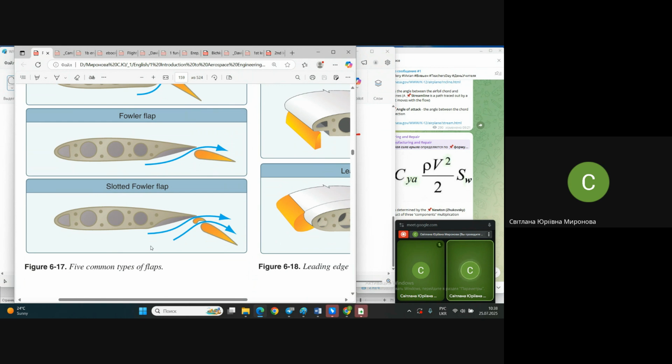That is a mechanically extremely complex thing, and here you see two links of the flap, like two pieces, but really it may be three and even four. The typical decision is three for big airplanes, and next we might see it in photos of airplanes. This slotted Fowler flap, on one hand, may increase curvature much more significantly than the plain flap, because you have these slots, and these slots result in better downwashing of this area during changing of shape.